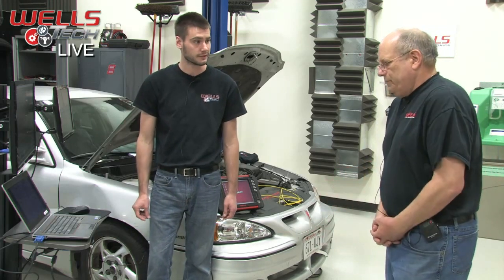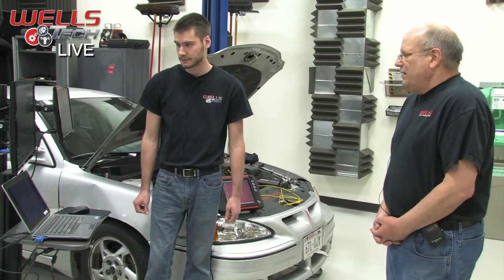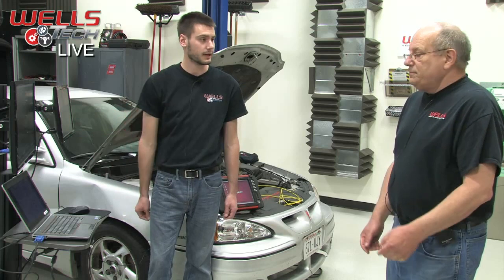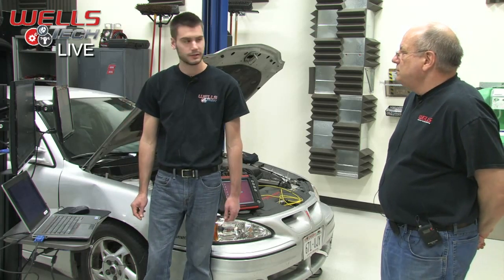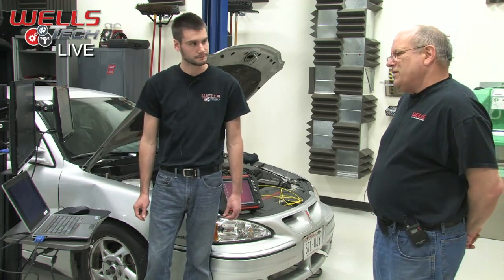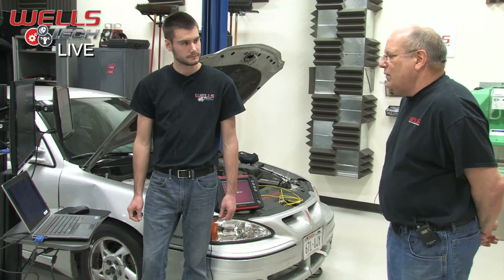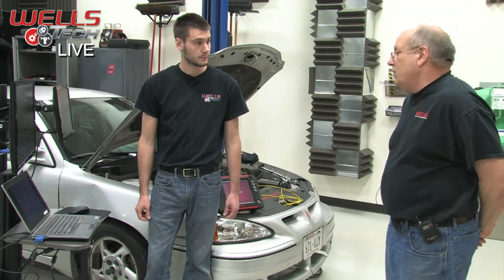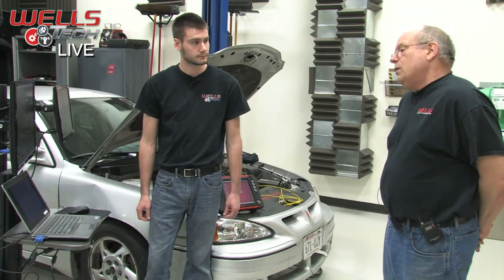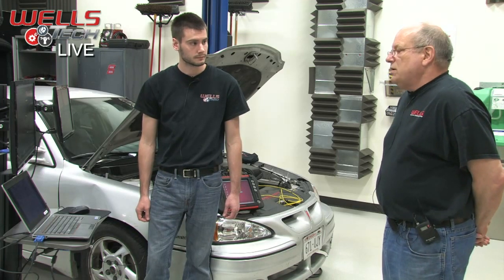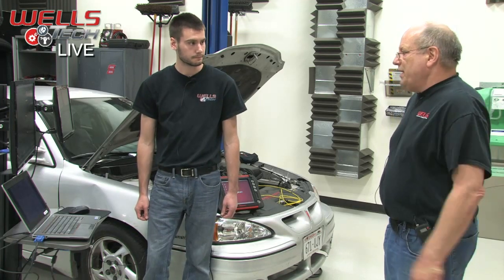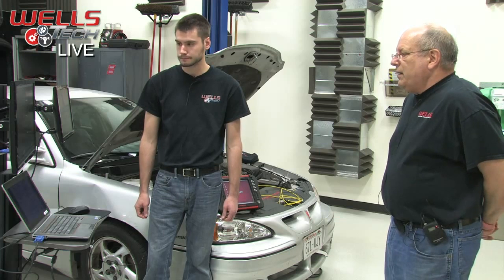It could really throw you off. Okay, very good stuff. This is a good pattern and everything, but it's not really telling the whole story of what that engine's doing. It's just a cam signal, and we don't know if it's actually coming on at the right time or going off at the right time at this point. We know that the cam sensor is sending out a signal, but that's all we know at this point.